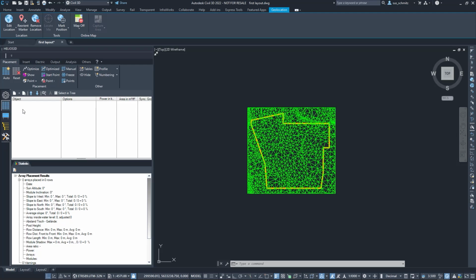If the placement list doesn't show the surface, even though the surface should be there, you should refresh the list. In that case, the surface entry should appear. Otherwise, please check the format of the surface. When the surface is ready, we can add boundaries, an outer boundary as area, and after that, the fields as closed polylines.